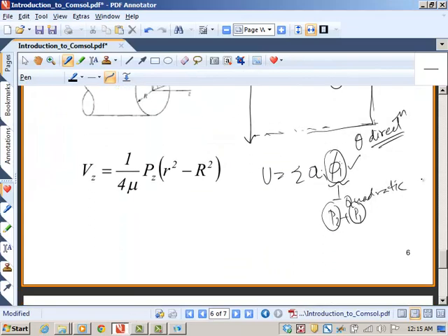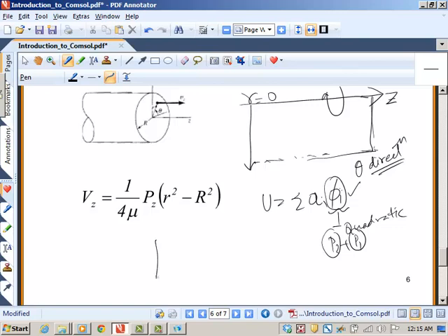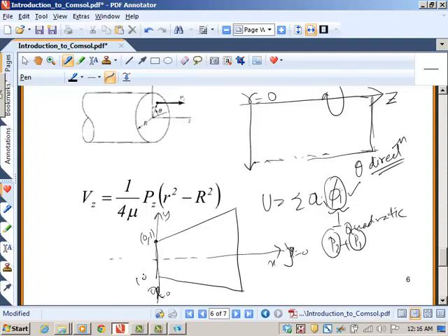So let us say I want to build this kind of geometry, with this x is equal to 0, and say this is your y is equal to 0. So let us write the coordinates for this. This is y axis, x axis. So I'd say this is 0 comma 1, 0 comma minus 1, and say this point is 10 comma minus 3, and this is 10 comma 3. So we have just written down the xy coordinates for these 4 points.